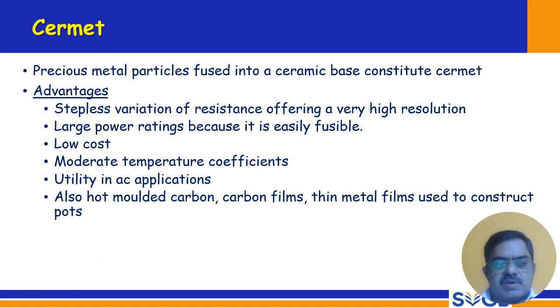So cermet: the precious metal particles fused into a ceramic base constitute cermet. So advantages: stepless variation of resistance offering a very high resolution, large power ratings because it is easily fusible, and low cost, moderate temperature coefficients, utility in AC applications. Also hot molded carbon films and thin metal films are used to construct pots.